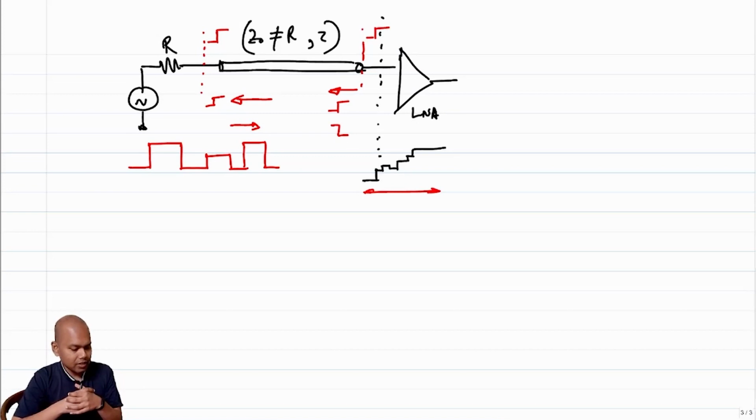Okay, so if that is the case, then given that the strength of the input signal that we get from the antenna can already be very low, right, of the order of minus 100 dBm or so, we do not want to see any more attenuation, or any more uncertainty in the reception of the signal, just because there are reflections and delays associated with the interface.